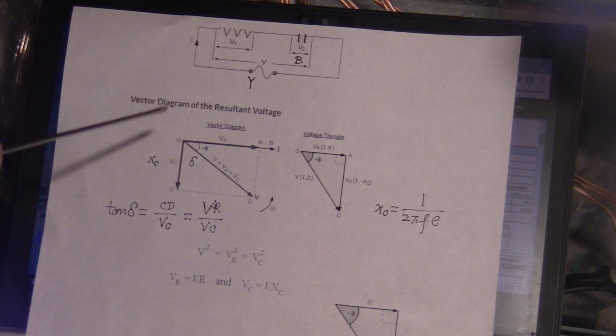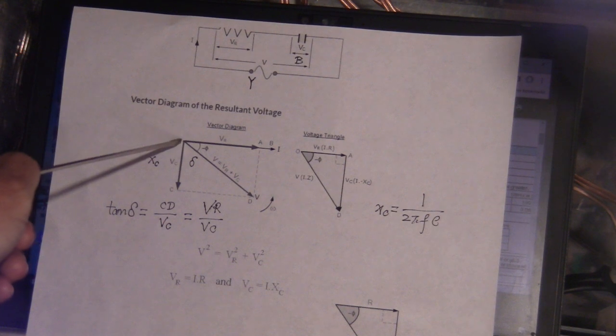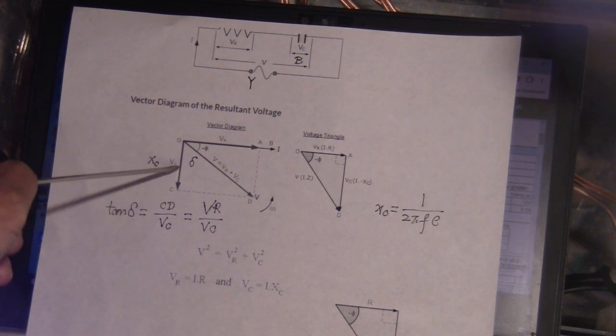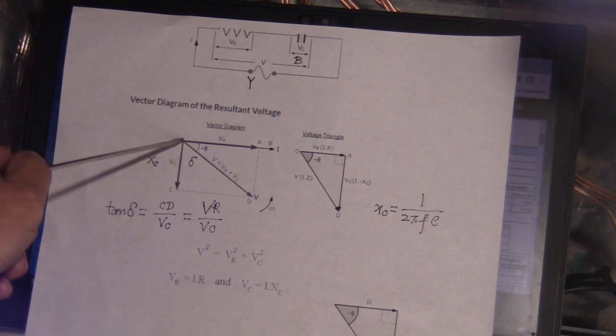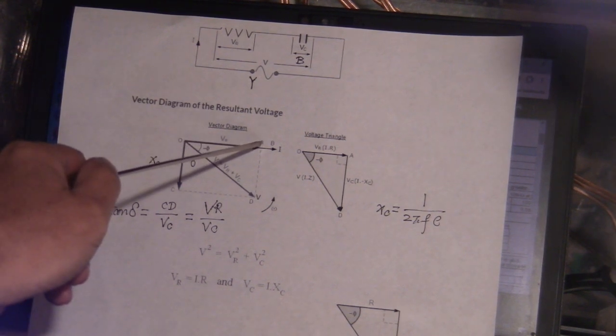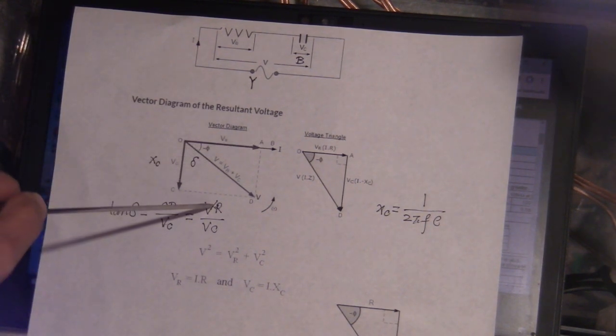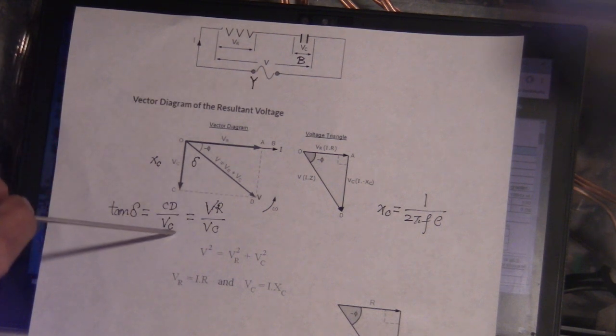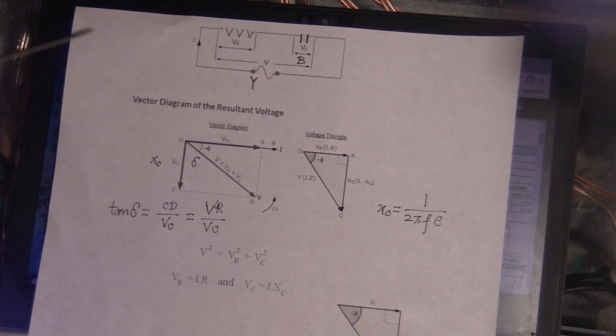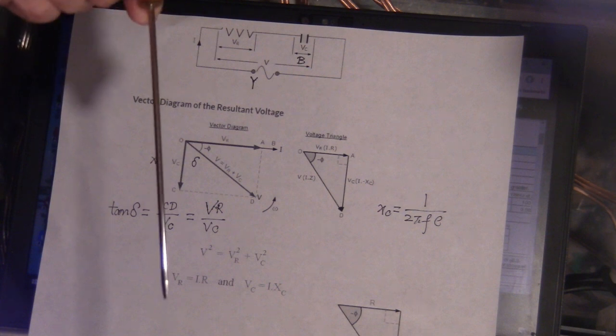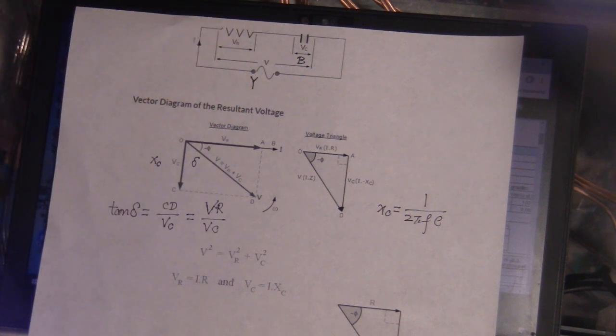Also sometimes they say the capacitor lost capacitance. What does that mean? If you lose capacitance, it means this thing gets shorter and this one, ESR, grows. I mean this one gets longer. Then in this equation, this thing gets bigger and this one gets smaller, and this angle theta is going to become bigger. So based on what this can tell us, this capacitor goes downward. And what is the threshold to replace it?